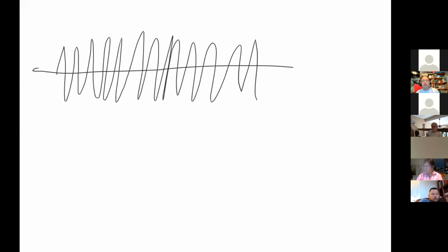Okay, modulation is the act of taking a radio frequency signal and changing it, modifying it to make it convey information. So let's say I had a radio wave with a frequency and an amplitude that looks like this. And it does not get turned on or turned off. It just basically operates at, let's say, 1 megahertz. Basically, this has no information on it whatsoever. It's always there, no information.